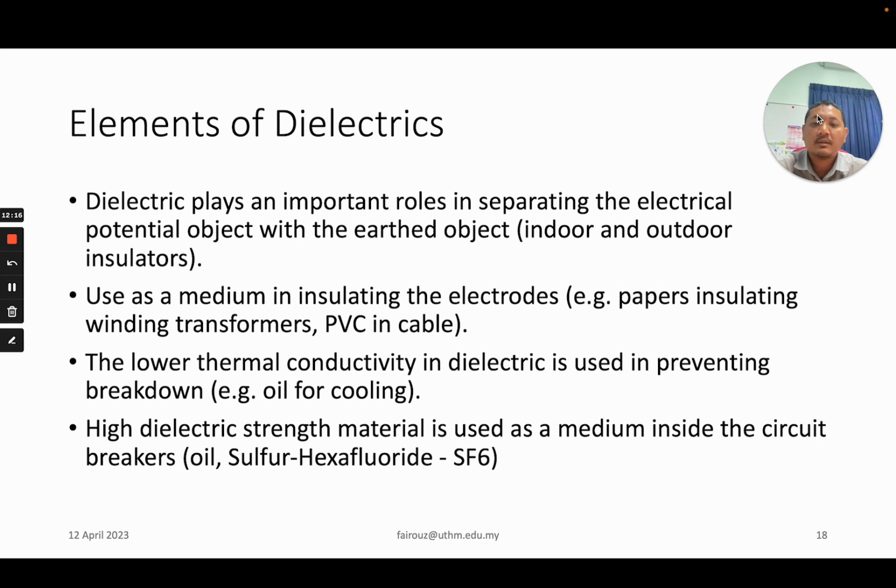In circuit breakers, we use air, but if we want to go for higher voltage, for 33 kV, 132 kV, 500 kV, we cannot use air as insulation in the circuit breaker, because air is usually used until, I would say, 415 V. Not sure if we have 11 kV as circuit breaker. Yep. Right. So for higher voltages, we usually use SF6.